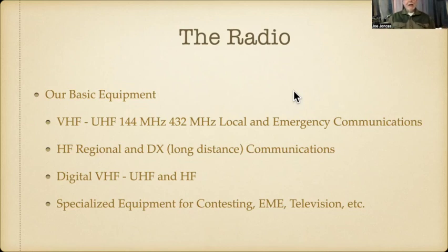But VHF and UHF, it's a straight line of sight. When the signal goes out, it goes straight. If it runs into anything, it quits. If it goes into the air, it goes straight out into space. It does not bend or reflect or do anything. So if you can see it, very often you can talk to it. I remember living west of Portland, up on the hill, and I could see Mount Hood, and I could talk to the Mount Hood repeater, which was a long ways off. But I could see it. So it was line of sight.